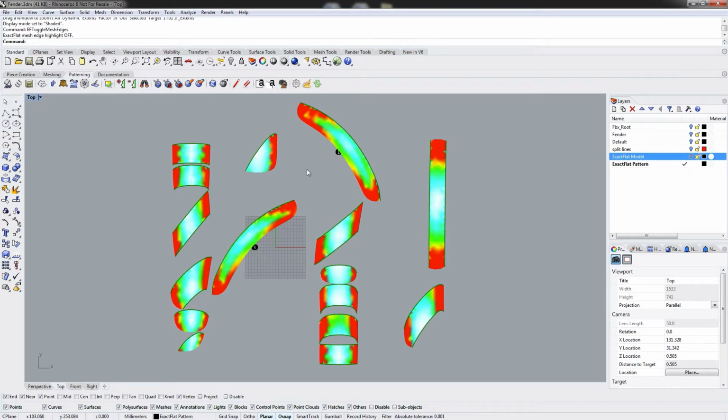So in ExactFlat, we've gone ahead and flattened using the flatten command, and really what we've done is started the flattening process using one of ExactFlat's pre-flatteners. ExactFlat is split up into a two-part flattener. Our first part being our pre-flatteners, and our pre-flatteners are very fast, very quick flattening algorithms that are designed to get you an unoptimized 2D flat pattern, and that's what we're looking at here.